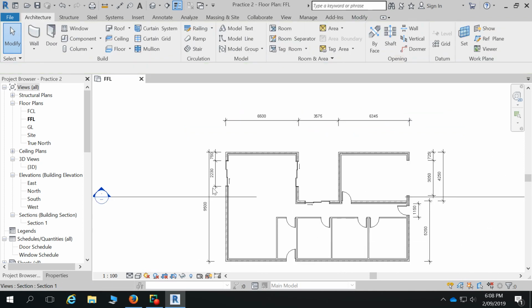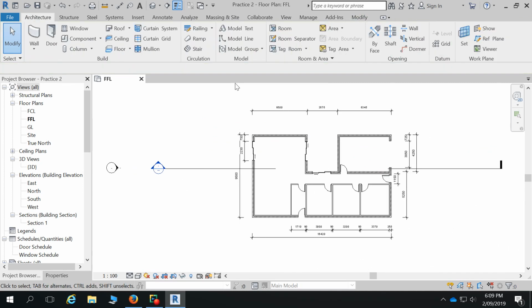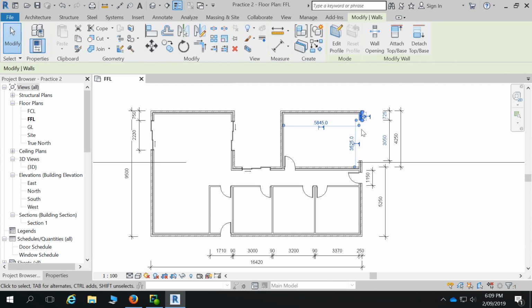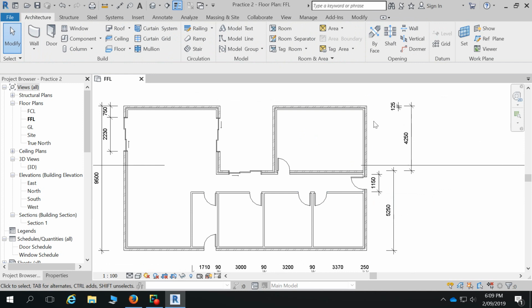So when you're setting up a building, rather than just use the temporary dimensions, these blue ones that come up, sometimes it's easier to put some quick permanent dimensions and use those to set your walls and window distances out, which is sort of what I've done here, which is where you had trouble with this end. And before I get to that, if I just delete that bit and trim that one back around the corner, everyone would have had something like that to start with, possibly.